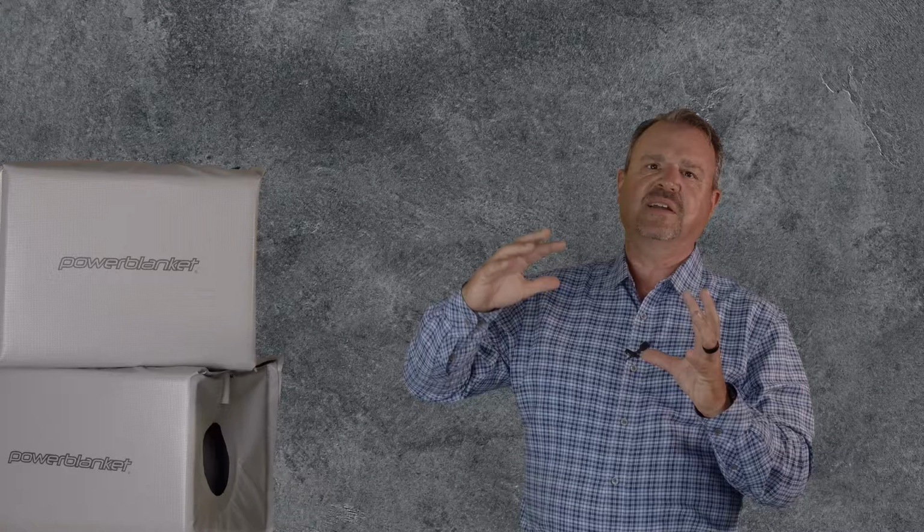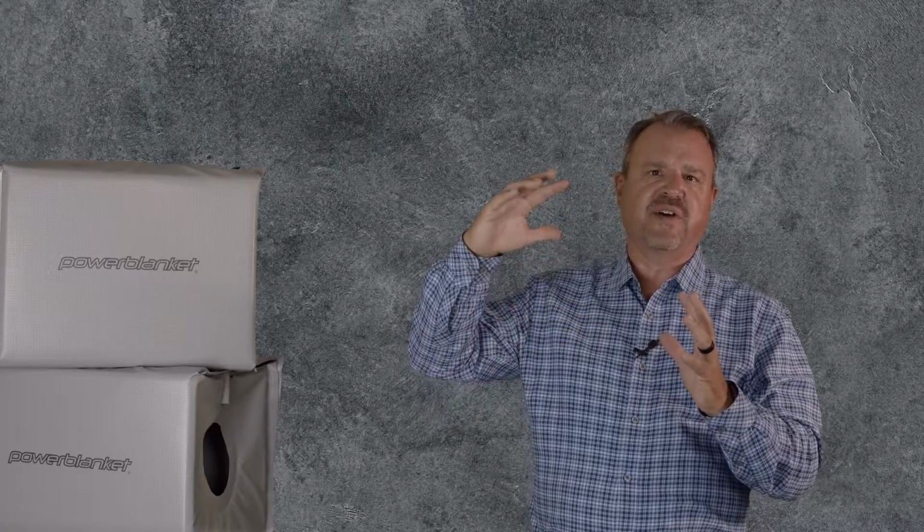On the other side of things, from a control standpoint, usually you've got a very large mass of product in a tank, a lot of tar or liquids of some sort, biodiesel. And when you apply heat to that process, it just doesn't heat up very fast. It's dozens of hours for it to change temperature. So the type of control that's most commonly used when we talk about the thermal loop is just an on-off